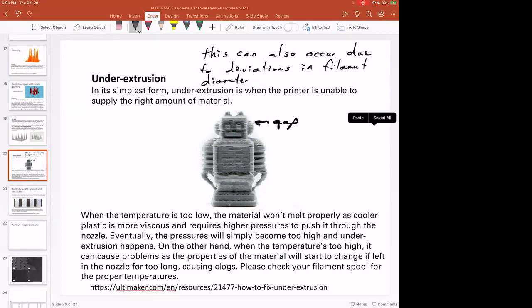In industrial material extrusion AM, it's really important to get a well-gauged filament with very consistent diameters, because the machine isn't measuring the flow rate of the material coming out of the heated liquefier. It's only measuring the length of filament that it's putting into the heated liquefier based on how much extrusion it needs. So it doesn't necessarily know how much polymer is in the heated liquefier. It just knows the length of filament that it's putting in.